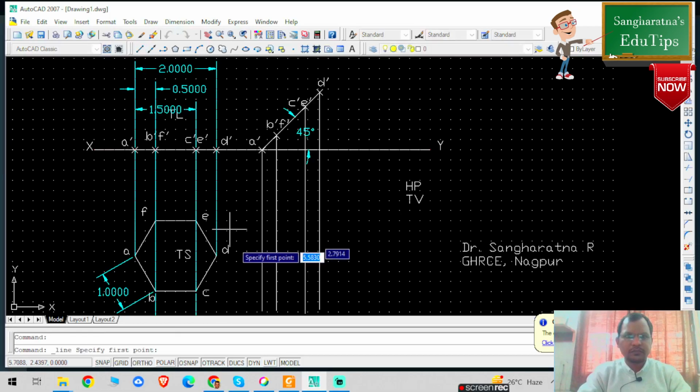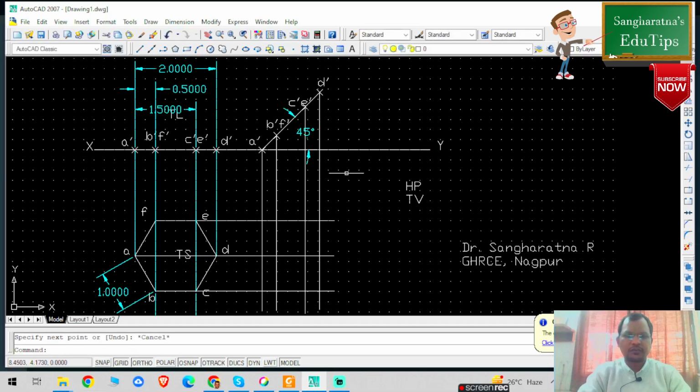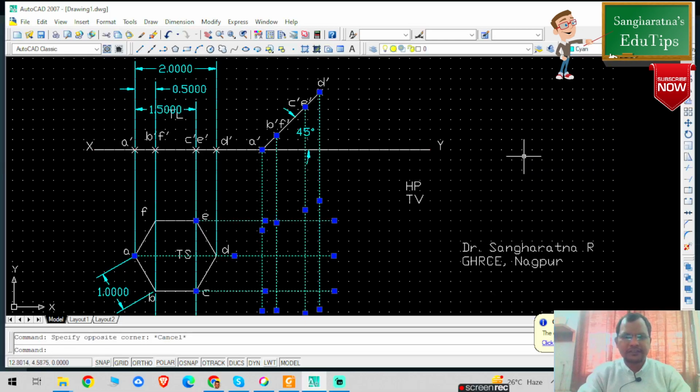Again, from this particular point, C dash, F dash and E dash, I need to draw a horizontal projector. Press escape. From this particular point A and D, another horizontal projector. From this particular point B and C, I am going to draw another horizontal projector. Now I am going to convert this projection line into cyan color. Press escape.